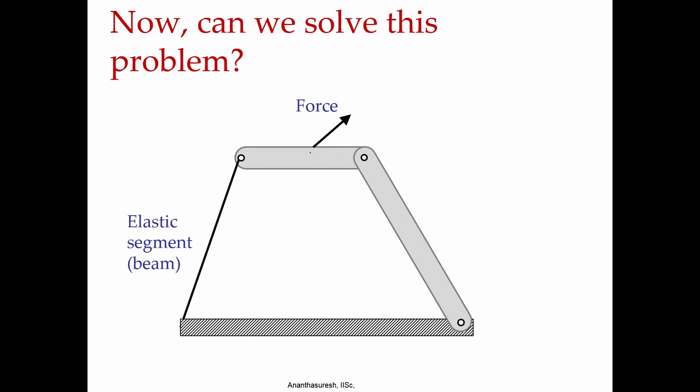That is, when we are given a force here and an elastic segment, can I do this? Instead of movement, that is function generation where theta is given and phi is there, now we are giving a force and we want some output. In order to do that, we have to somehow capture the elastic behavior of the cantilever beam beyond just the kinematics. We have discussed in this lecture the kinematic abstraction of the large displacement of a cantilever beam, but we also need to look at its elastic behavior, meaning what resistance this cantilever beam offers to the deformation.